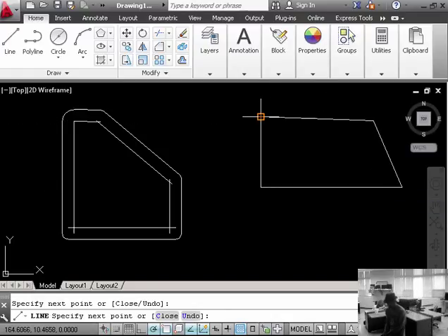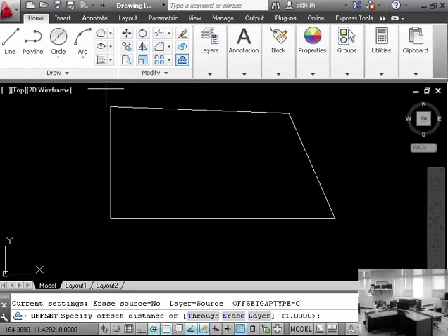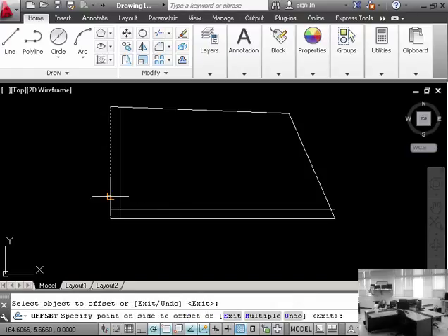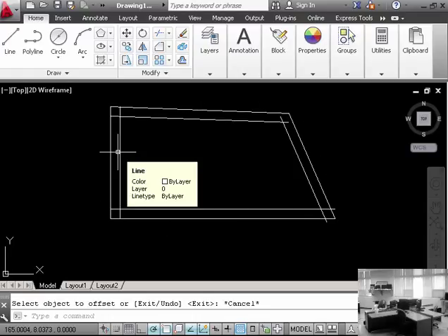Let's say we have some scrap. I can't cut on the outside edges of the plate, but I cut the inside. So we use the offset command to create the safe zone in which to design. So as long as I design my parts within this zone, I know that I don't have to worry about any of the equipment burning out or flashing out too close to the edges. So great little tool. Anyway, again, those materials are provided individually, and you can go check those out, but that's kind of how they work.